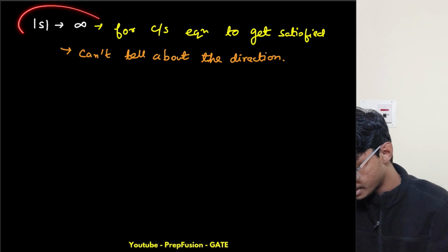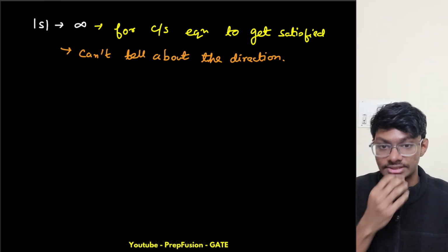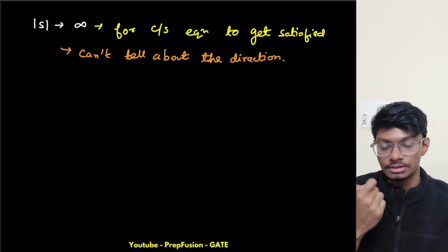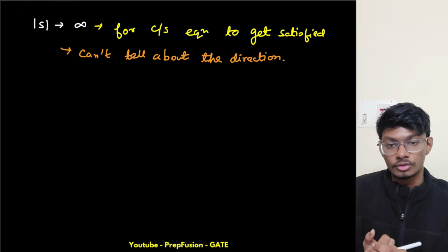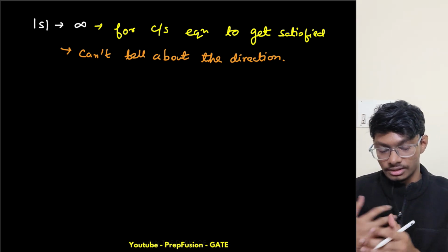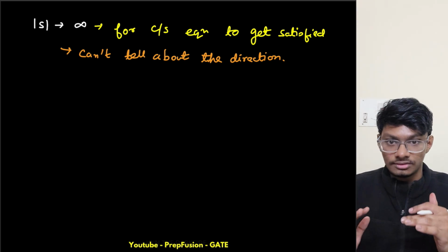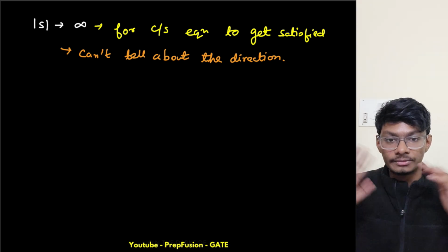Now what does this mean? This is not an actual 0, still I'm getting a 0, like this is like a 0 of the OLTF. As we will understand later on, my root locus starts from the poles of the OLTF and terminates at the zeros.